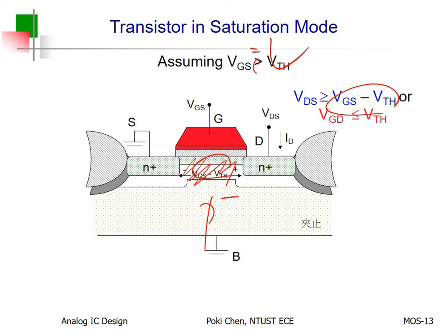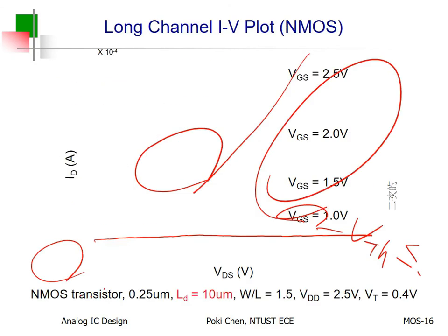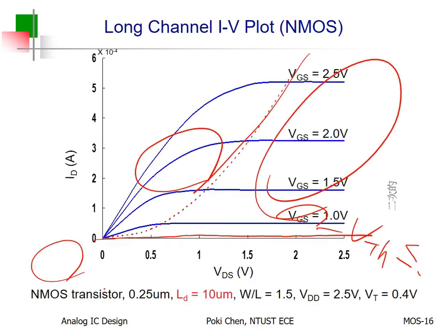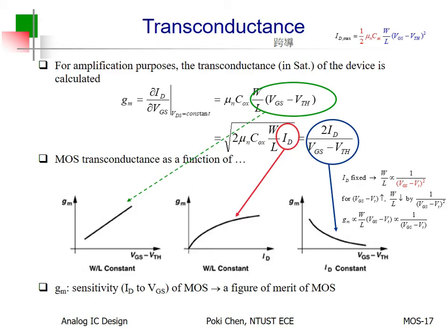Yes, it is a semiconductor. It is not any kind of insulator. So even when VGS equals VTH, don't expect 0 IDS. Sorry for that. It is still a little bit conductive, since it is a semiconductor instead of an insulator. So in theory the channel depth equals 0, but it won't be non-conductive. It just becomes an intrinsic semiconductor, and a semiconductor still conducts a little bit of current. Don't be misled.